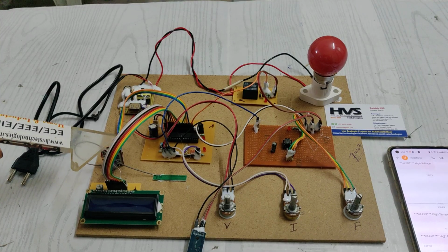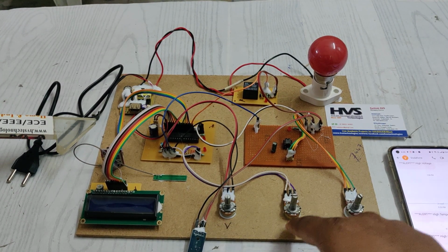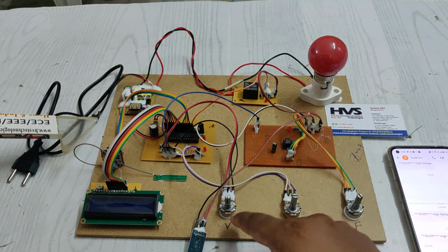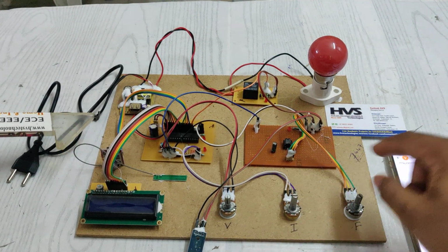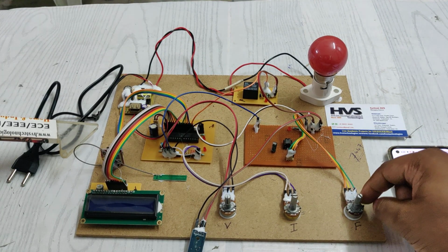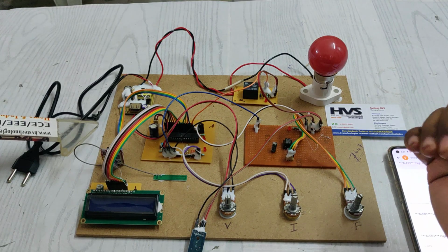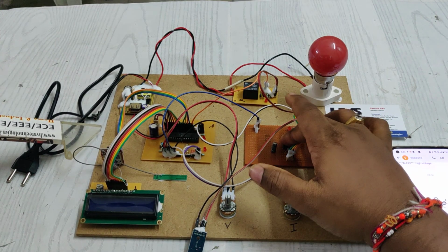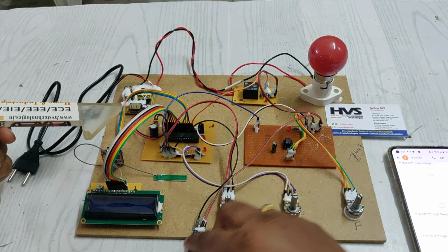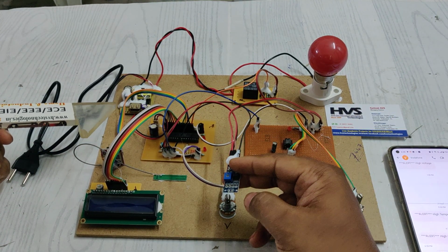GSM module. The major components: we are using 3 potentiometers. In that, these two are used to measure and vary the voltage and current. And for varying the frequency, we are making use of this potentiometer. By varying the resistance values, we change the frequency using this 555 timer IC circuit. The variable frequency is input to the microcontroller, and the temperature sensor continuously monitors the temperature in power